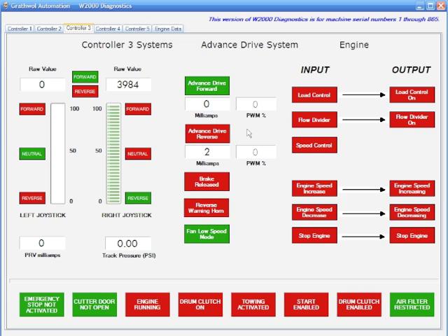and this, in my opinion, is probably the most valuable use of the software, a short circuit situation. Okay, right now you've got a short, and watch what happens. Okay, notice that the milliamps are varying. It's very erratic, but here's the key right here. The PWM is still at max condition. It's still giving a full output, and the milliamps to the pump are varying.